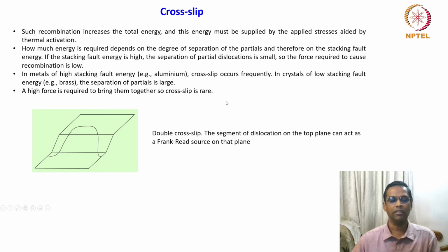That means dislocation activity or glide motion is confined to individual planes, not cross slip. In very simple terms, the three-dimensional mobility of dislocation is highly restricted. This is another way of looking at it, right?